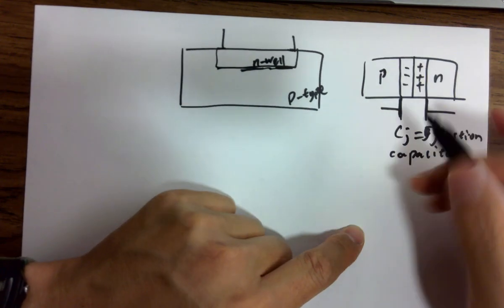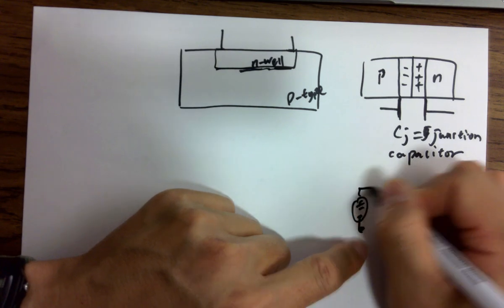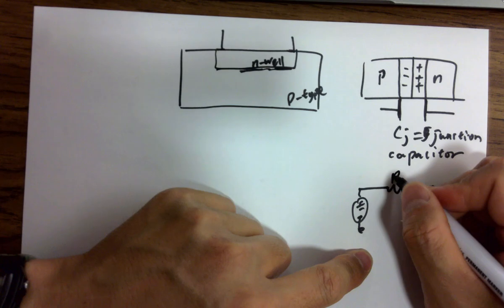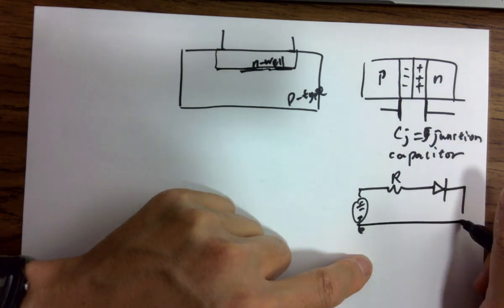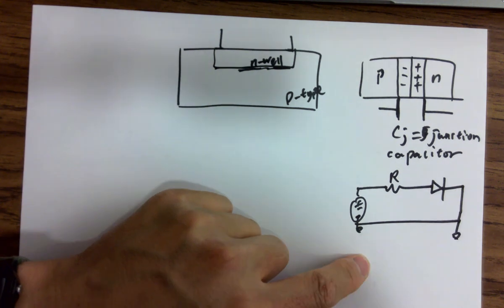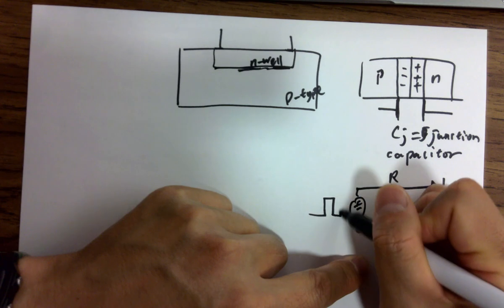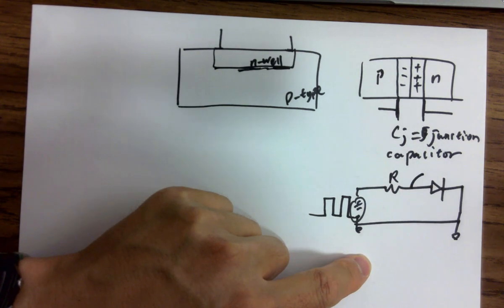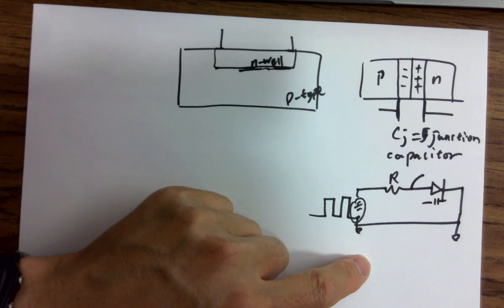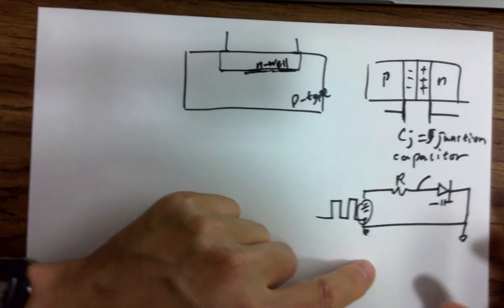So that's why when you are having a circuit, for example, like this, that's the power supply. Have a resistor which is limiting the current, so it's not burning that diode. You have a circuit like this, and you are driving this one using pulses, and you're expecting what over here? Delayed response. Time delay, because this has a little cap inside. There's a capacitive load inside the diode, and that is why.